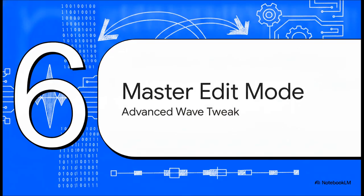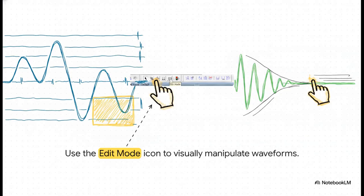And finally, Section 6, Mastering Edit Mode for Advanced Waveform Tweaks. Using menus to manually type in binary values is totally fine. But let's explore a way faster, far more visual way to manipulate your simulation data directly on the timeline itself. Keep an eye on your toolbar for this specific button, the Edit Mode icon.